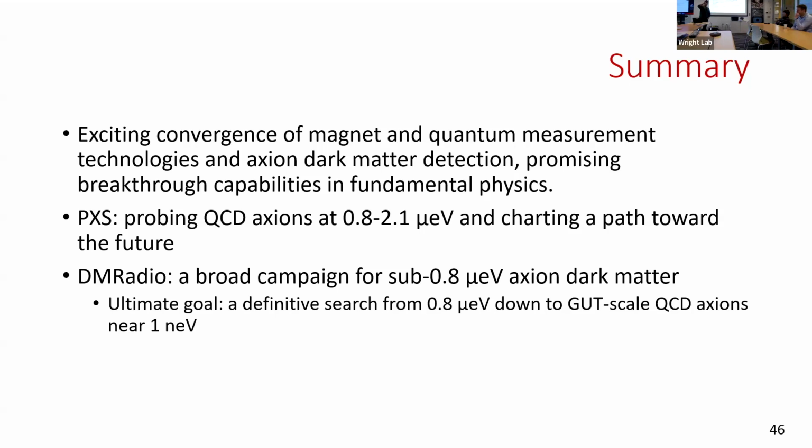So we have heat sinks on both 40K and 4K. The heat sink at 40K, we have these copper leads because we don't have room temperature superconductors. And so there's many watts of joule heat generated that we can't get down to 4 Kelvin, because if it gets down to 4 Kelvin, our cooling power is much less there. And then the temperature would shoot up, our magnet would go normal, which wouldn't be good.